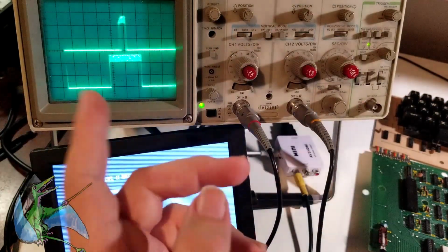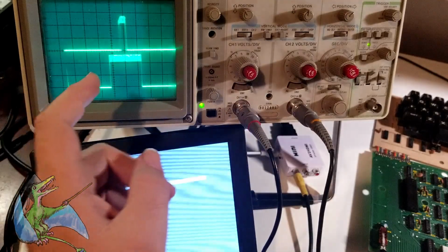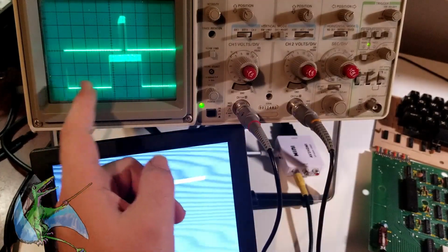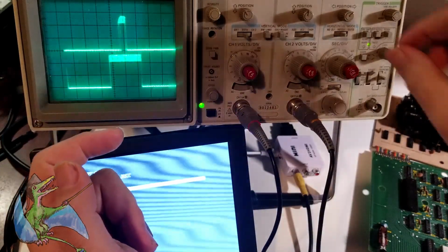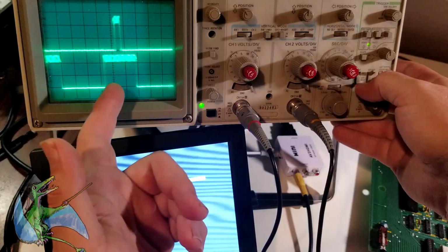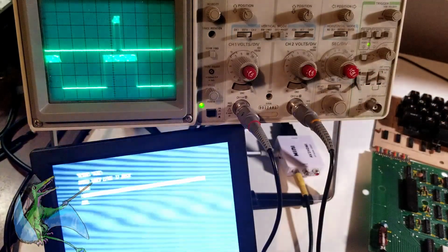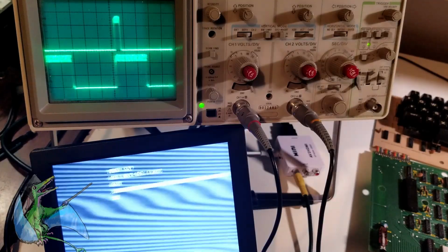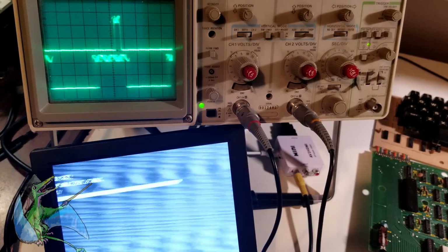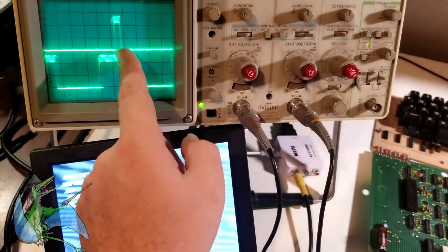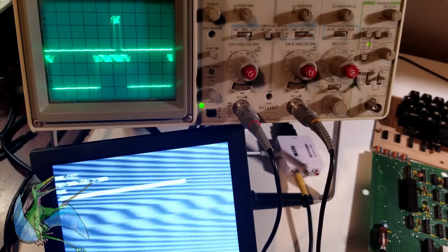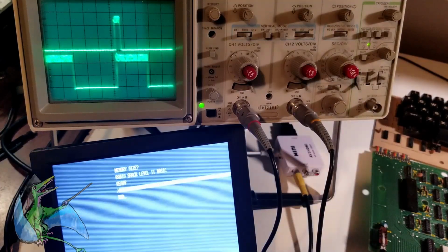So why am I explaining this? First off, this explains why, when you saw I moved the knob back and forth, this went back and forth but this stayed stable. Just for fun, if we switch the trigger so we're triggering off the other one, you notice it gets messier, because this one is messier. Now if we crank this around again, we'll see the bottom one moves around, because we're now triggering on the falling pulse of this. But it's shakier because this is shakier, unless it's cranked all the way over, in which case it's looking pretty good.